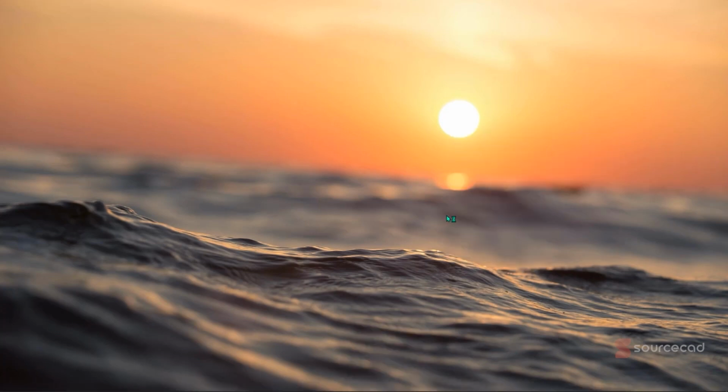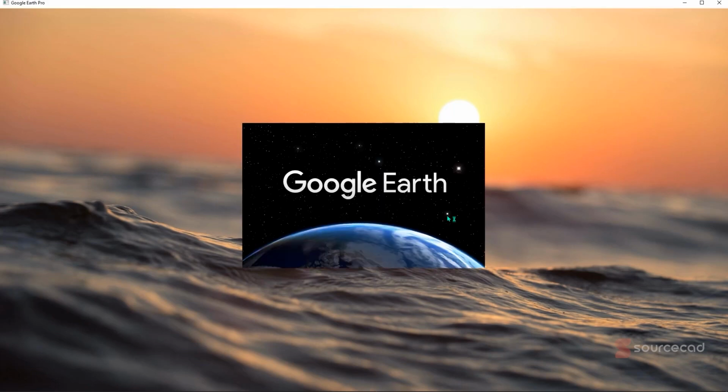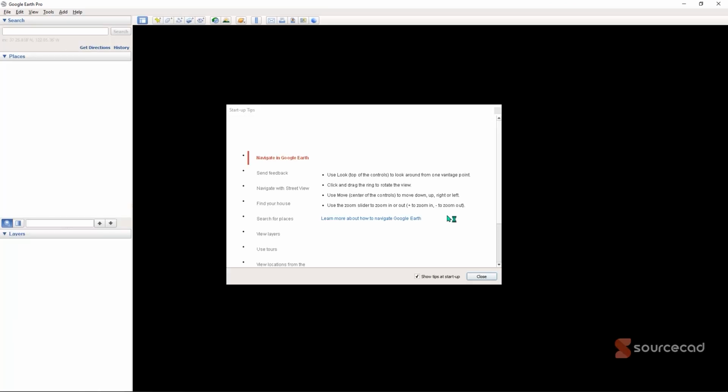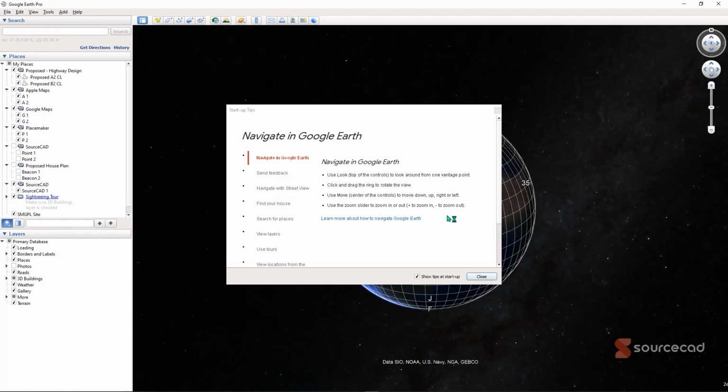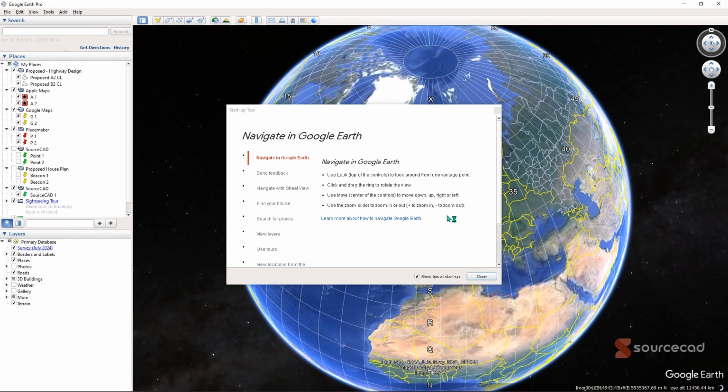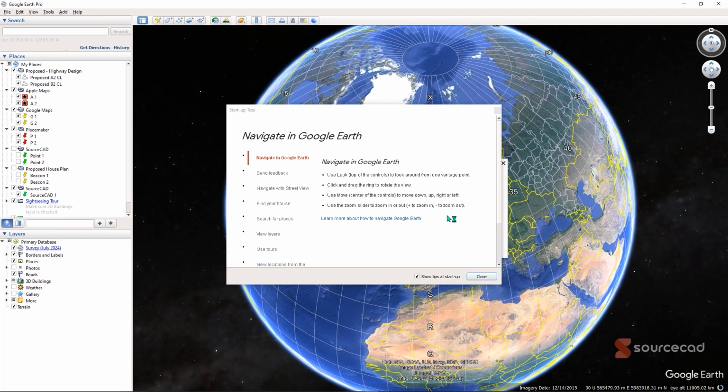The main purpose of doing this is to get our survey data, which will be just a rough representation of the process that usually happens. In most cases, the surveyors go to the site with their survey instrument. It can be any instrument, maybe a total station. It can be maybe GPS, or so many items that can be used to collect real-time data on the Earth's surface. And then it will be collected into one specific document, let's say an Excel document, where you can manipulate and clean your data. Once your data is clean, you can import it to Civil 3D.